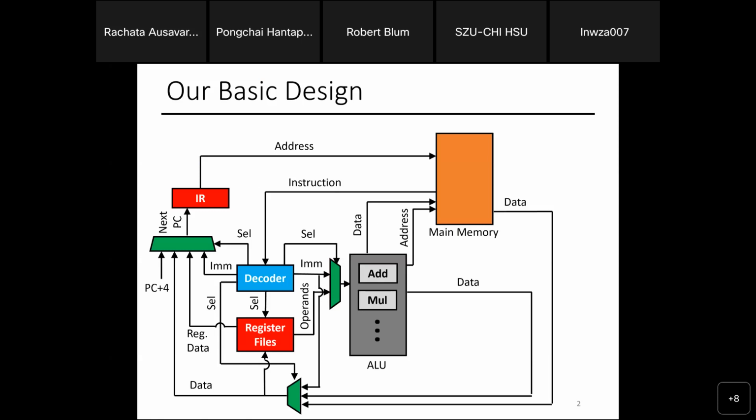Again, the key things here: you have the fetch unit, which goes to the memory and fetches the instruction. You have the decode unit, which takes the instruction and figures out what I am supposed to do with it. The decoder sends control signals everywhere on your CPU: make sure I take the data from here and from there, add, subtract or multiply them depending on the instruction type, or go get data from the memory, depending on the instruction. The decoder handles that.